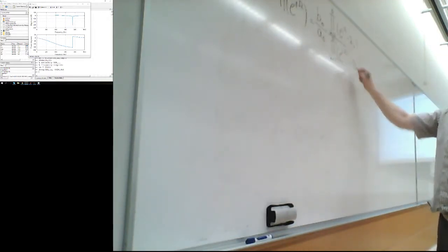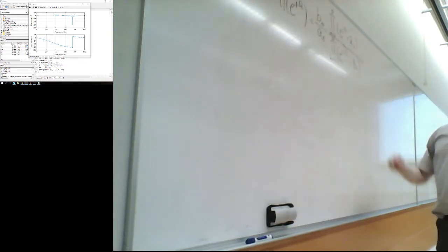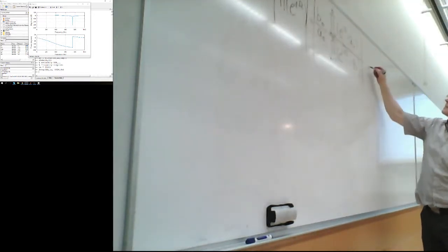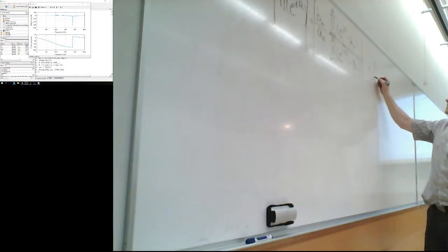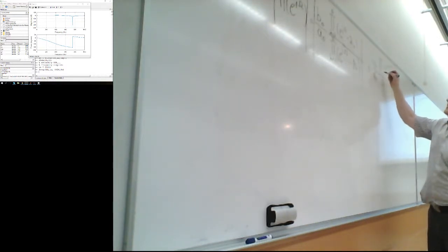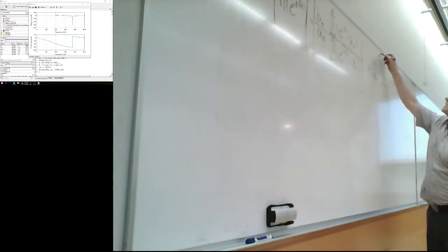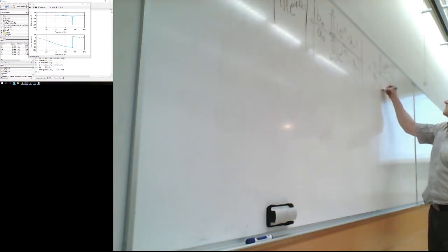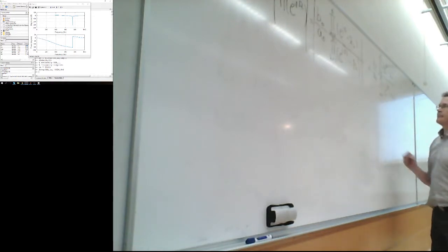Then you take the amplitude response: B0 divided by A0. On the numerator we have the product for k from 1 to n of the absolute value of e to j omega minus zk, divided by the product for k from 1 to n of e to j omega minus pk. Good.